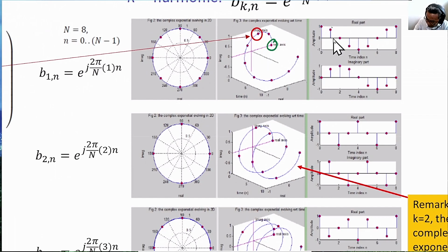The second point, we move by pi over 4. So the cosine decreases as n increases, and the sine increases. The sine is represented by the positive j omega axis. So it's going up the j omega axis. Therefore, the cosine from this point moves down, but the sine goes up, and that is why in one sample it rotates anti-clockwise. So this is the reason why omega equals pi over 4 results in an anti-clockwise direction.